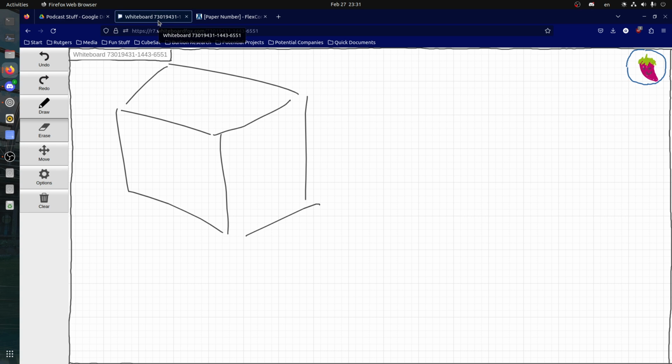They'll try to align each other, right? But if you have a magnetic field and a rotating wire, or like a rotating coil, it'll generate a little bit of EMF, and that EMF is detectable. So a magnetorquer, in theory, could be used to detect magnetic fields. Not saying it will, but it's possible.